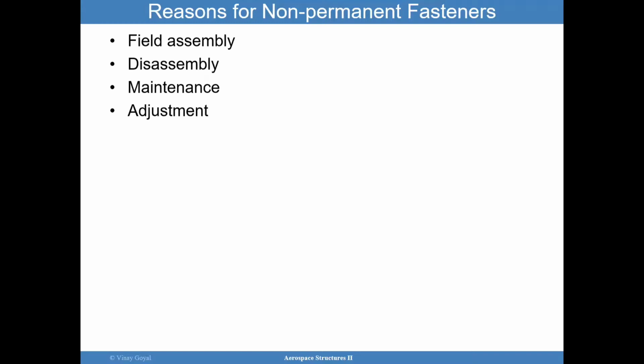However, bolted joints do carry a disadvantage, and one of their disadvantages is weight. And so you ought to balance the benefits of going to a bonded design versus a bolted design versus a welded design, and determine what is the best course for your design. But typically bolted joints do offer advantages from the standpoint of maintenance, disassembly, and so forth.